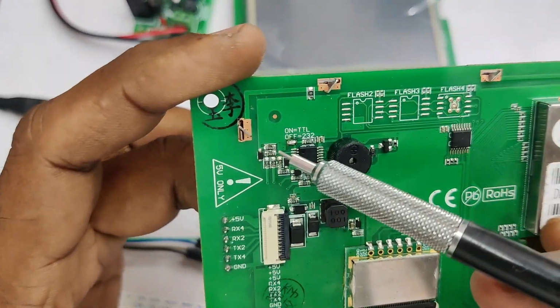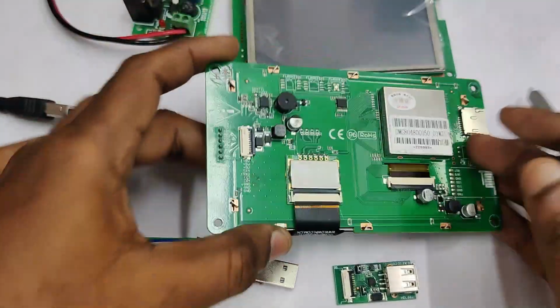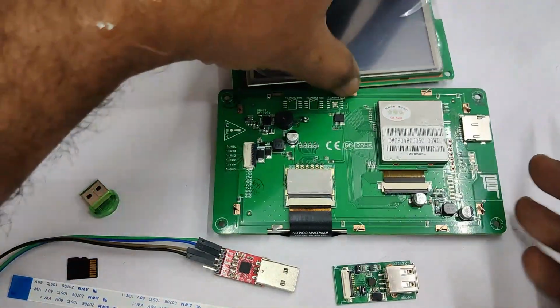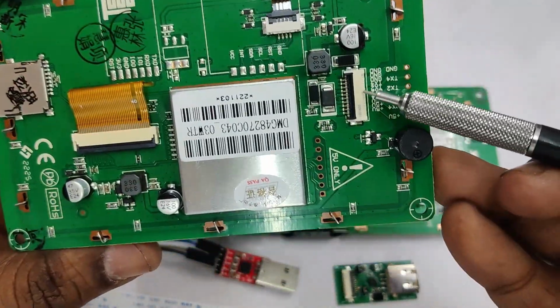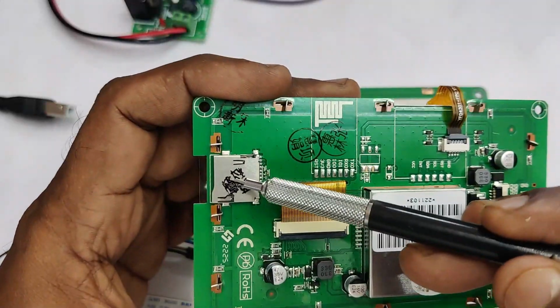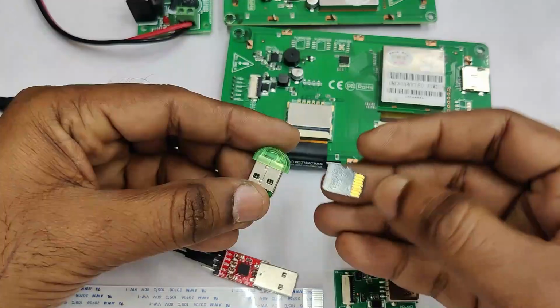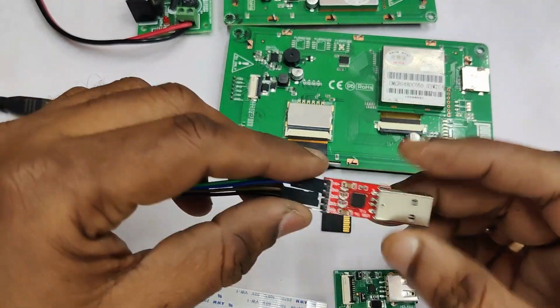In some boards you have to solder these 2 points, that is to enable the TTL output at these pins. In displays like the 4.3 inch there is no such solder. Directly at the 6 pin output you can interface with the Arduino. So you have to take note of this. In higher end displays you have to solder that, and you need one SD card.